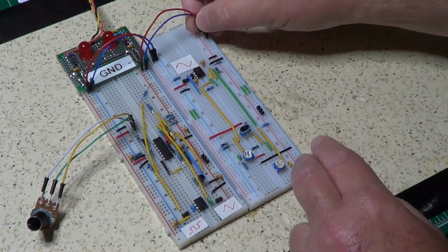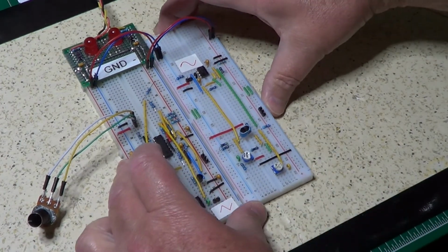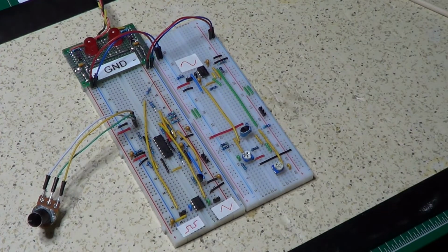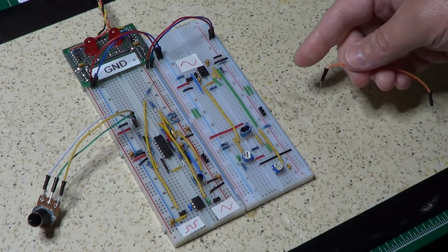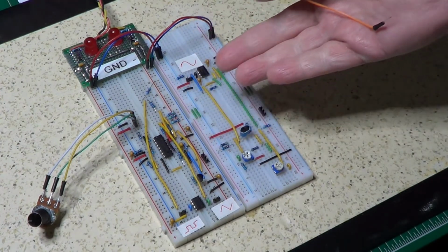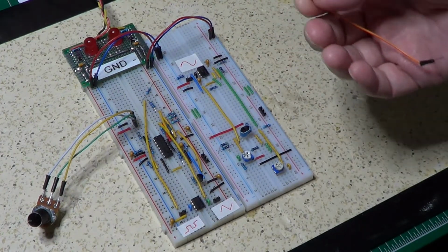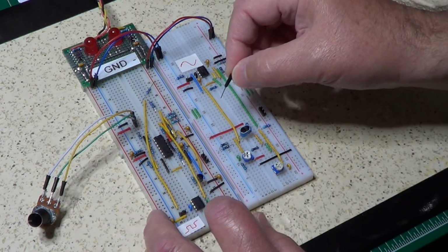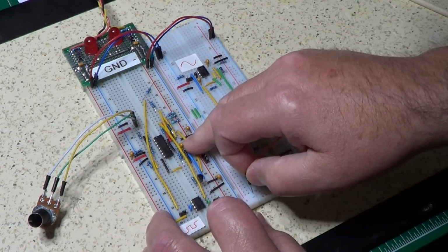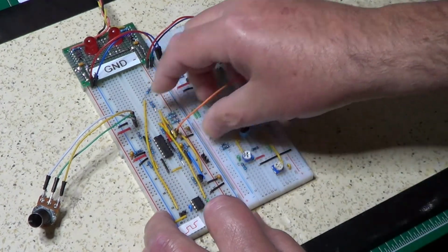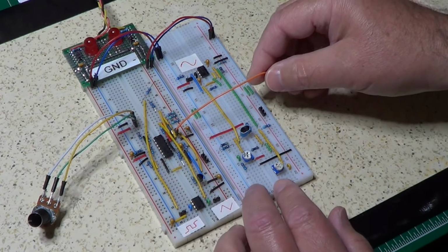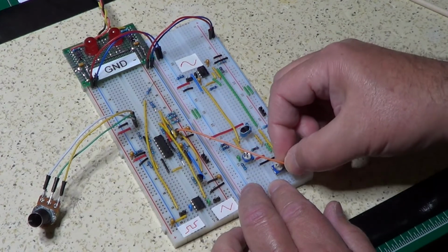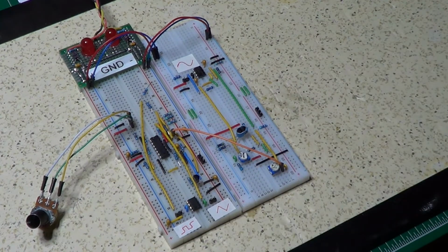With this. And now we have to connect the triangular wave output from this point in the middle directly to the input of this other system, so we can basically use it as a base for creating the sine wave. And to do that, we have to go on the pin right over here, and on this other side we have to go to the pin right here. There we go. This should allow us to have everything in place correctly.